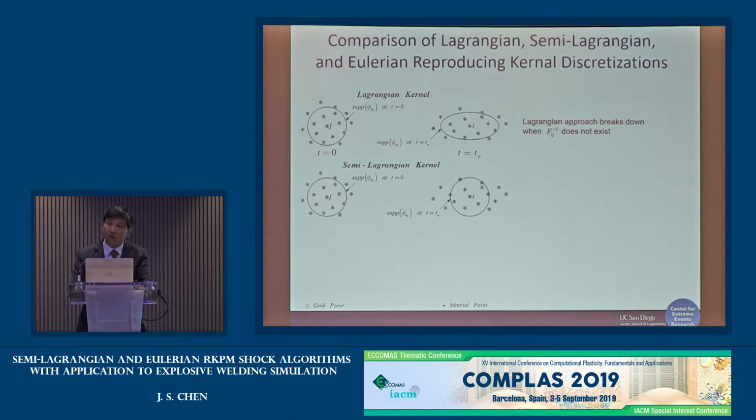But the shape function supports do not attach to the material. So you could have different neighbors at different states of deformation. This gives you the flexibility of redefining the neighbors depending on the mechanics of what's going on in the physics of the problem, right? So for example, when a crack happens, you can redefine the neighbors depending on the crack orientation and so forth. But still, the mathematical points are attached to the material point. You just define the supports at the current configuration.